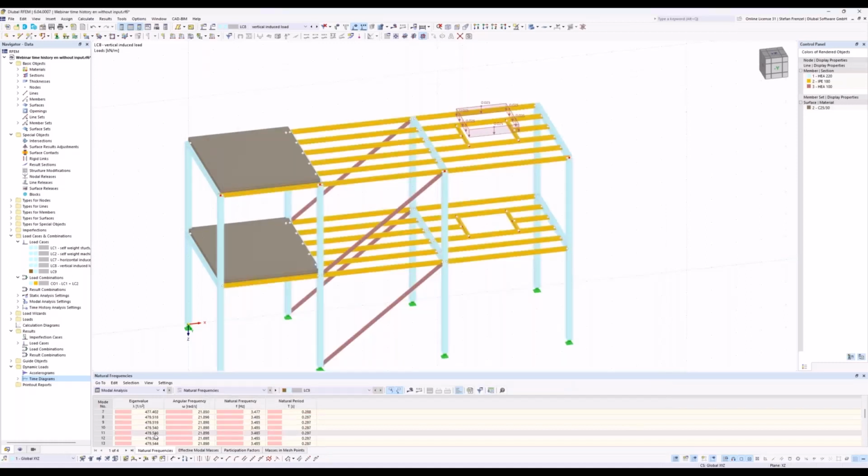The next step is just to show you that we also have an angular frequency of 35.4 here. So it's near to 35.2. That means it could be that I get a resonance for the whole calculation, because the horizontal part is my horizontal load. If I have a look at this eigenvalue 35.2, I just have to go to load case number 9.